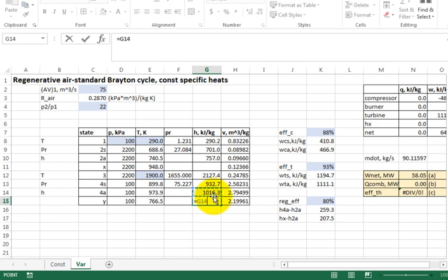That's going to be the enthalpy at state 4 actual minus this actual enthalpy change. And I can calculate the enthalpy at state X. It's going to be this enthalpy 757 added to the 207. All right, at this point my temperatures are off. That's a bad formula, but I'm going to just drag this copy down, because this cell used temperature as a function of enthalpy. Likewise, this one's temperature as a function of enthalpy. And to clean up the temperatures down here, the same thing. So those all look good.